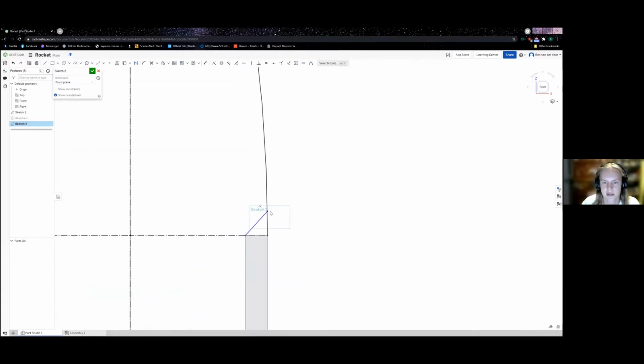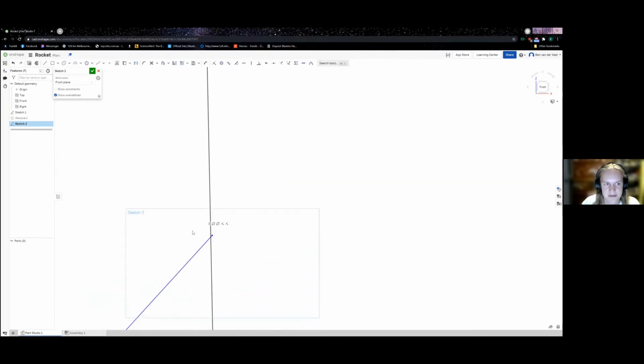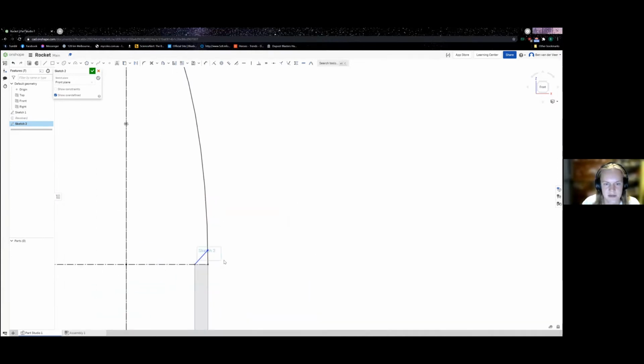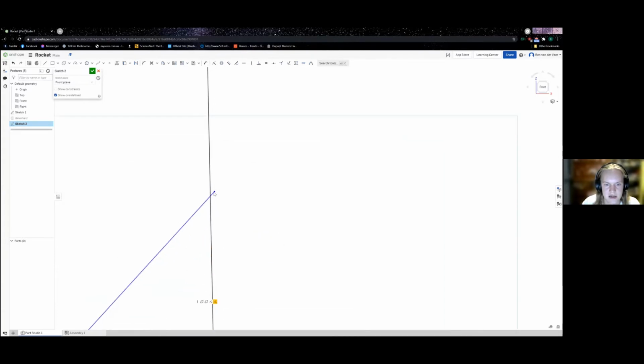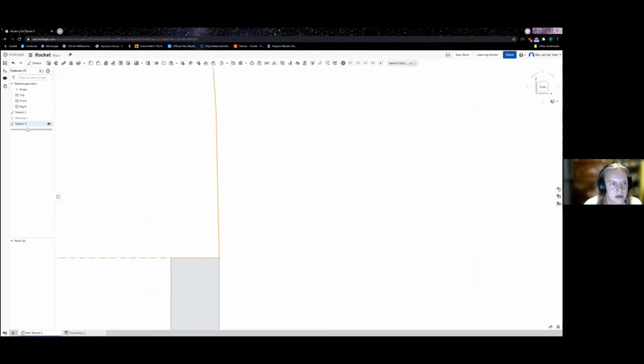Okay, so here we're seeing, I believe, an artifact of the tessellation quality of this part. So basically, instead of drawing an ellipse, it's approximating an ellipse. So while it's telling me that these lines are coincident, it's not actually showing up on the model. Part of the fun of 3D CAD modeling, though. Let me see if I can. Any Onshape pros know how to force better tessellation on parts?